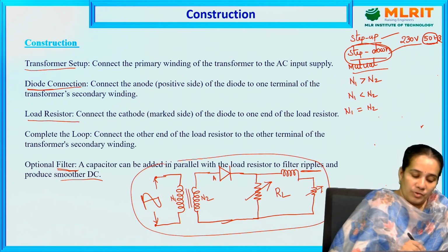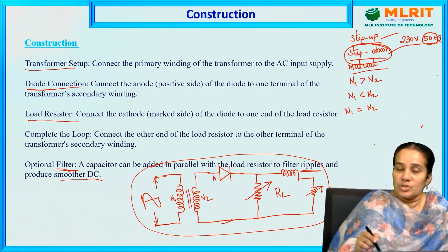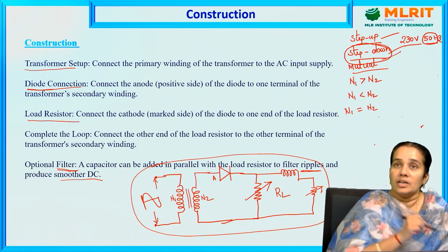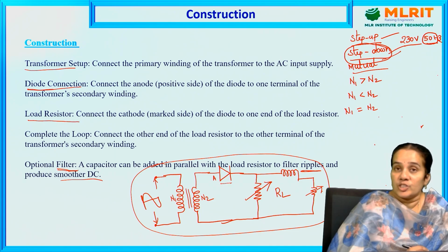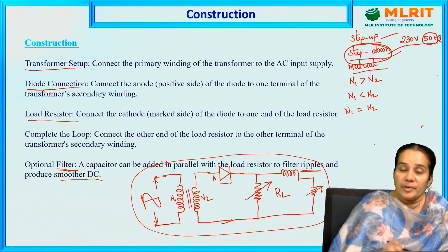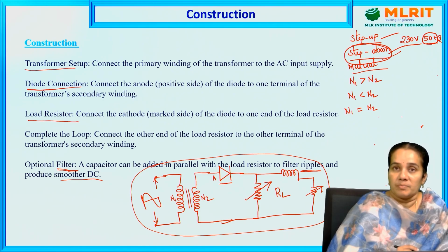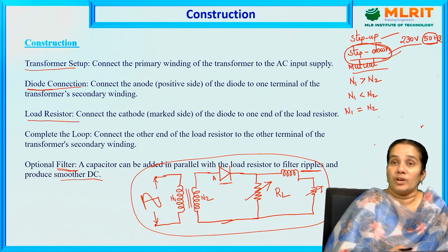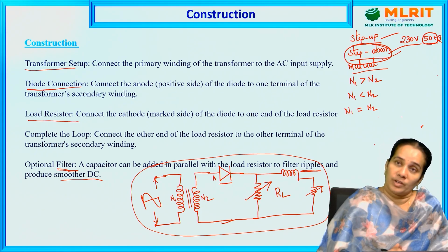The half-wave rectifier requires one transformer, and we are using the step down transformer. The next device is the PN junction diode. Here we use only a single PN junction diode, which rectifies only one half cycle, and the output is connected to the load resistance. The rectifier will not produce pure DC, so to get pure DC, the output of the rectifier is connected to the filter.